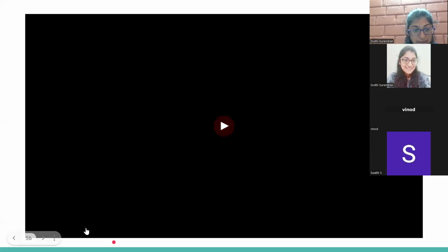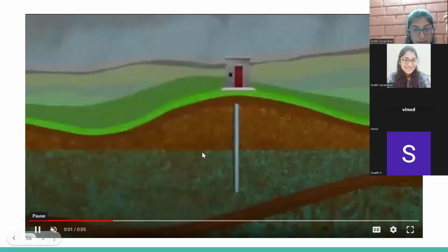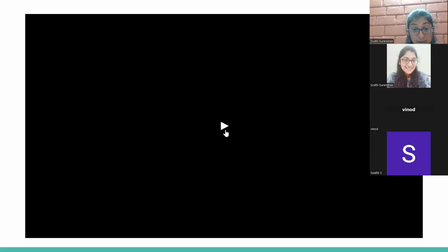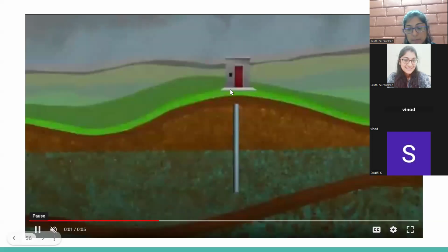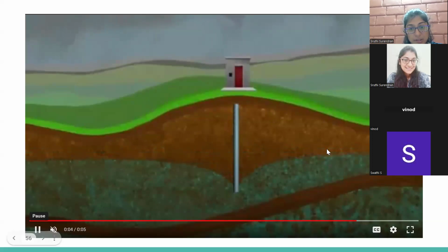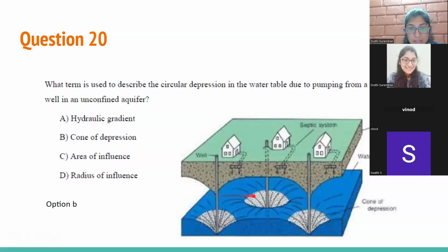It is going to have a particular curve such that the water in this aquifer is going to enter into the pump and the well water is going to keep increasing. And this curve is called the drawdown curve. So from a three-dimensional point of view, if this is the well and water is being pumped out of this well, water is going to follow a radial motion into this well from all the directions. And this curve is called the drawdown curve.